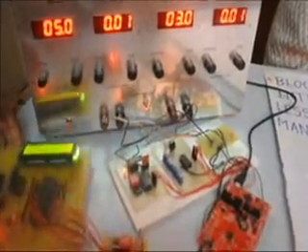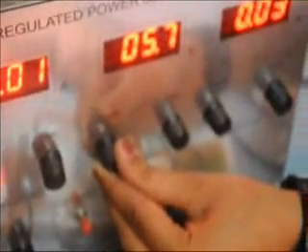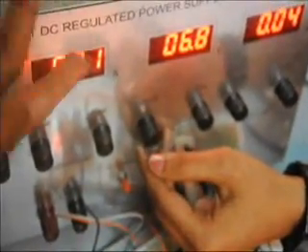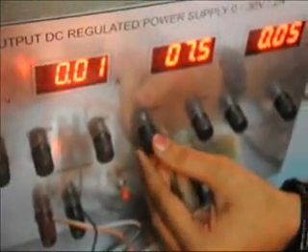As the voltage is increased, we can see that the data transmitted by the INA138 is displayed on this master board, which shows a current of 40.42 microamperes. Further, when we increase the voltage to a higher level, the current increases to 52.12 microamperes.